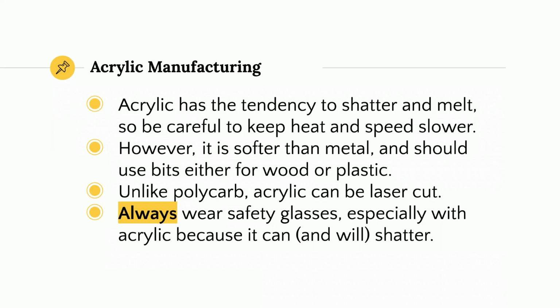Unlike polycarb, acrylic can be laser cut. So it actually works really well. So if you have a laser cutting machine or a laser engraving machine, putting acrylic in there works perfectly. If it's big enough, it's actually probably preferable to do that because it's less likely to shatter.